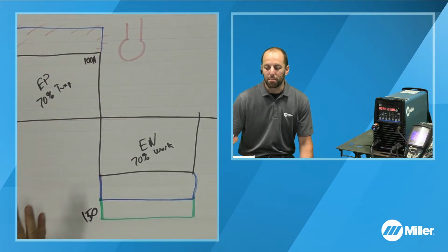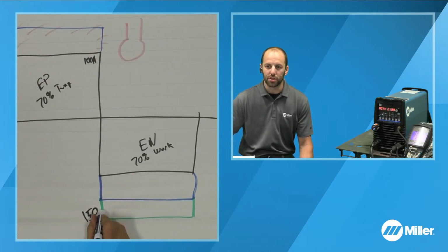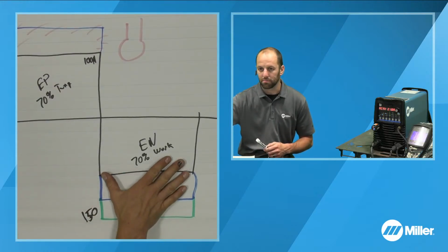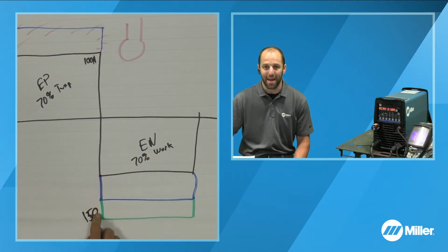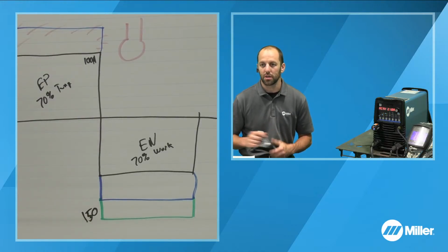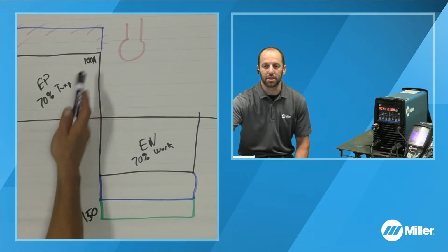So the benefit of using electrode negative is we can increase the amperage, or the heat, down into the workpiece. Not in relationship to time, but in relationship to amplitude or magnitude, to get us that extra penetration, because amperage is what we know drives penetration, while limiting the amount of heat on the tungsten in the cleaning action.